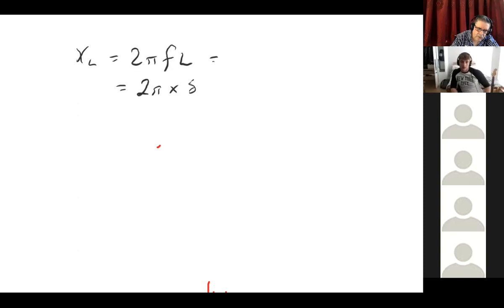Hang on, perfect. XL, 2 pi FL, 2 pi times 50 times 159.2 times 10 to the minus 3. And the answer to that is?